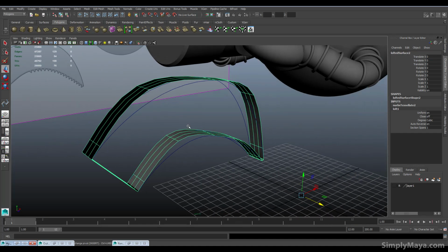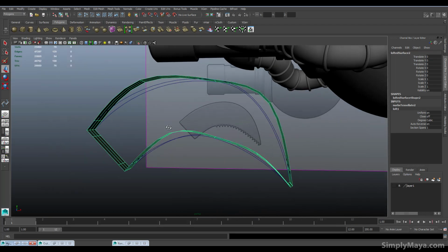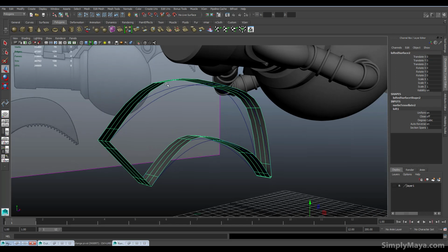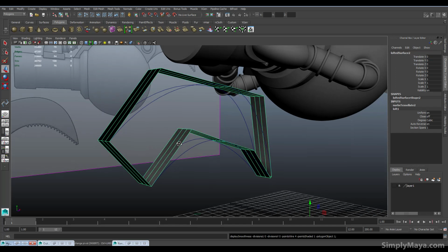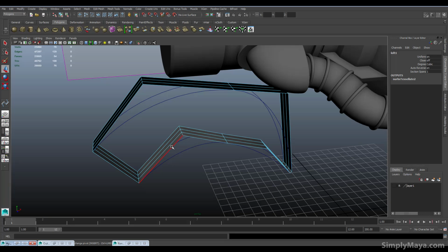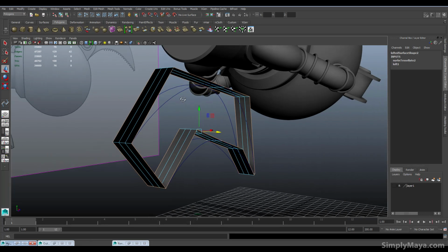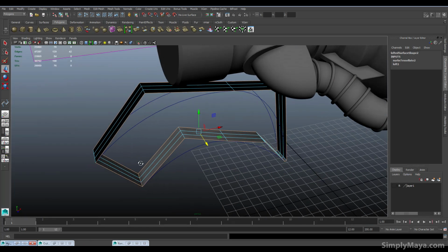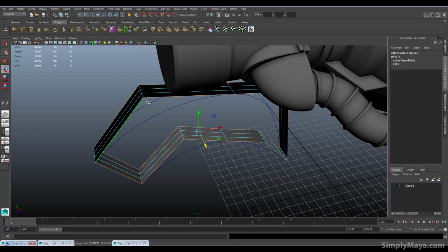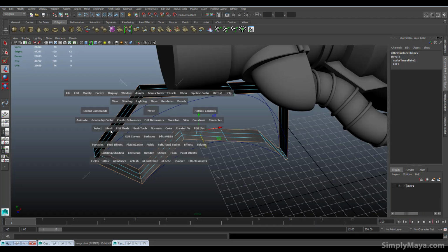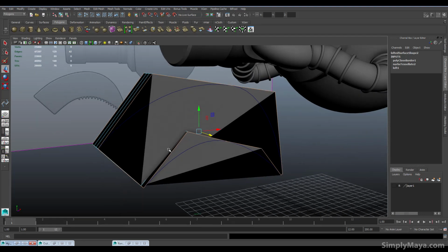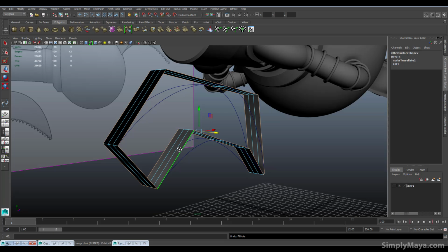So a couple of things we can do now, and one of the first things I want to do is to just get a face on this. Now, because I intend to smooth this, I cannot simply select the entire edge and then hit fill hole, because that will indeed fill the hole there. But it will cause other problems too, especially during smoothing. In fact, let's take a look. Mesh, Fill Hole. Okay, so that's just not going to work for a start.